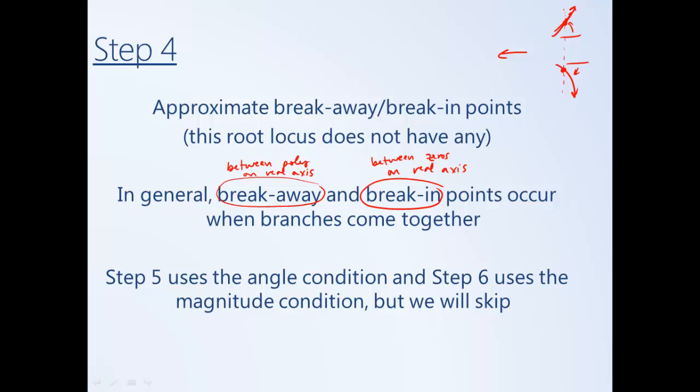So for example, in this root locus you can see that if you increase k enough, the closed loop poles will move from the left half plane into the right half plane. So this is a conditionally stable system. There are values of k for which we will place the closed loop poles in the right half plane and the system will be unstable. In order for us to examine these properties, we will use MATLAB.